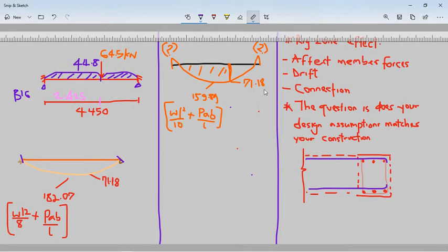But generally, if I also apply the principle of moment redistribution, then maybe if I have like 25% moment redistribution, if I deduct 25% from here and I split it into the support, that can also help to model my assumption in this case.